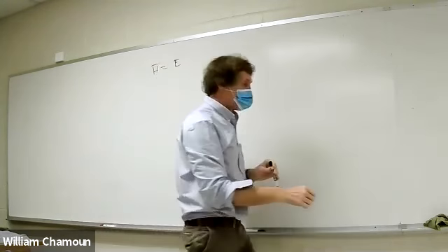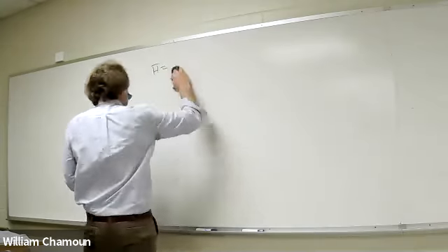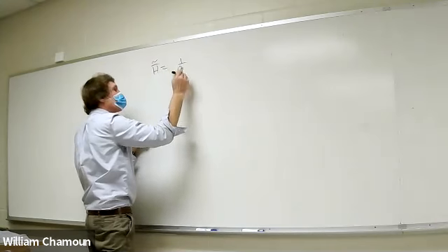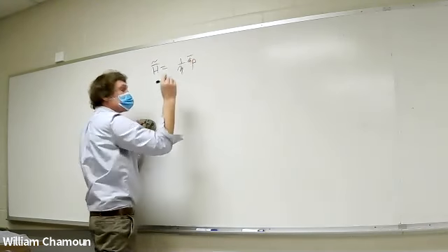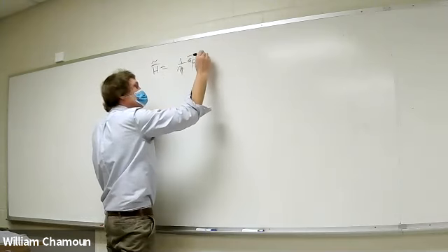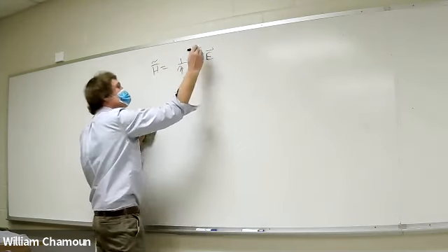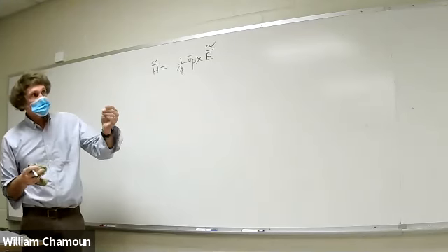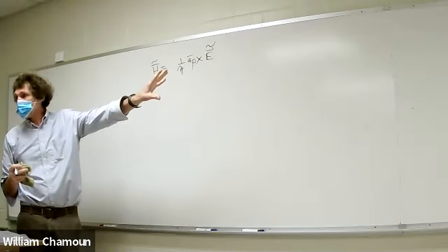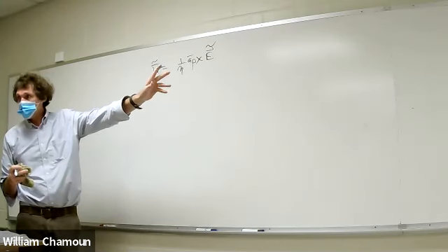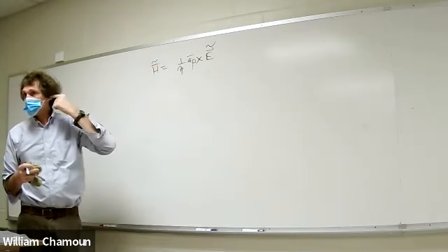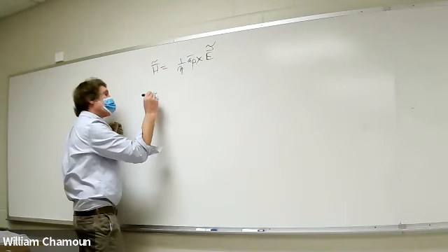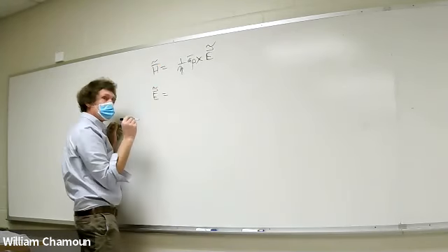It's 1 over eta. These are phasor terms, 1 over eta in that region. Unit vector in the direction the wave is propagating crossed into E. So this would be H field if you had E, correct? You can get the direction of propagation just by inspecting the wave, the Z prime. You can get that. You all with me? Either incident, reflected, or transmitted Z prime. Correct, class?